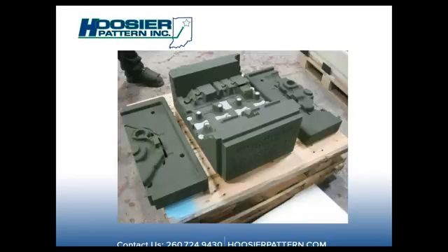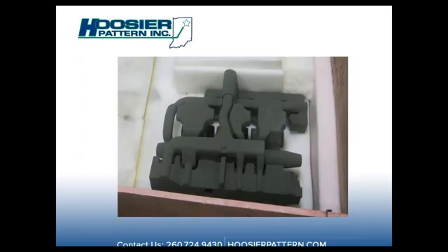Here's some examples of that casting where Steve is just talking about where there's chills. You can see the chills in the mold. There's multiple pieces, and combining the cores for the complex core assembly, that would have been multiple cores. That way you keep all your accuracies.